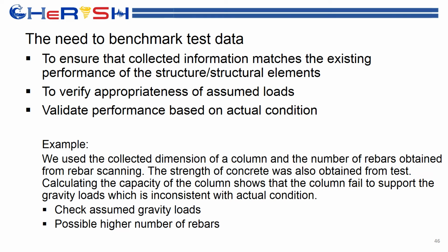we calculate the capacity of the column, right? We calculate the capacity of the column from the obtained number of reinforcing bars and the obtained compressive strength. And then when we check the capacity and compare it with the actual demand, the column fails the gravity assessment, right?